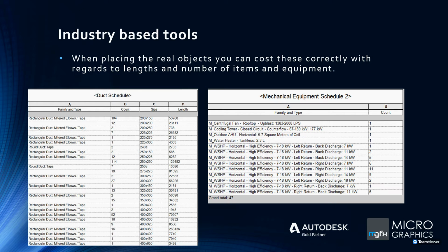There's just one of them, but you can add an additional column C, get a value, and then multiply that value by the count so that you can do calculations to create costing. So if there's now a second rooftop fan, then that column C will update with double the amount of value or cost.